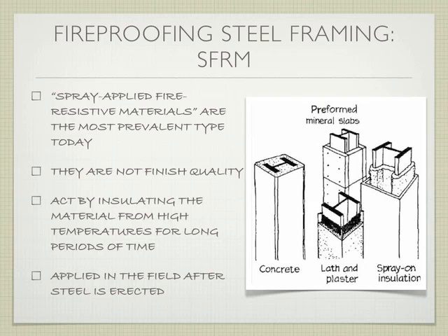A good example is a parking garage, and I'll pick on Target again because it's very obvious and a lot of people have been there. When you go downstairs in the Walnut Creek Target parking garage and look up, you will see this spray-applied fire-resistant material covering all the steel beams. It's really easy to put on, because you're insulating the steel from the fire after it's already in place.